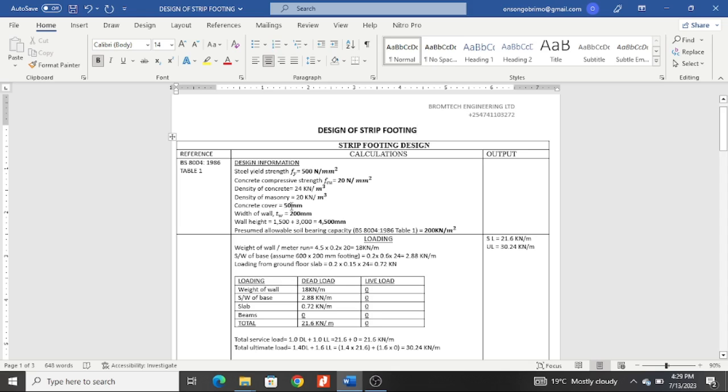This one we actually design for depending on where you are. But in grounds where we don't have minerals that attack concrete, and where we don't have salts in groundwater, we normally do 50, and in moderate exposure conditions, you could do 40 to 50 millimeters cover.